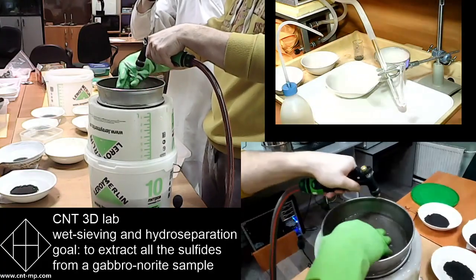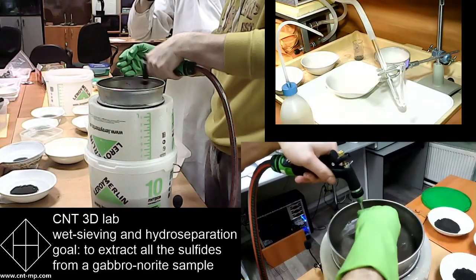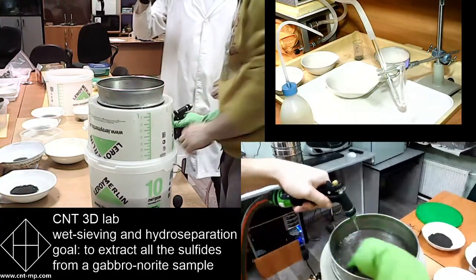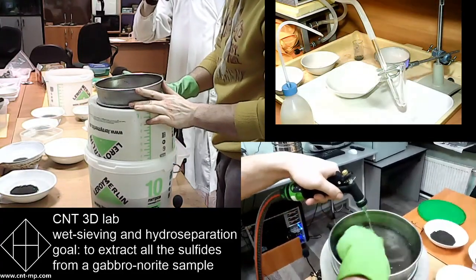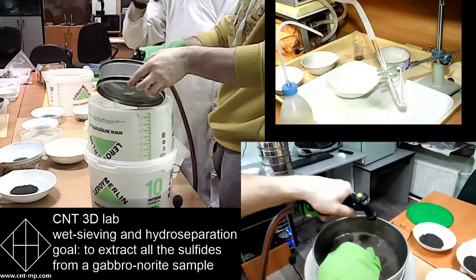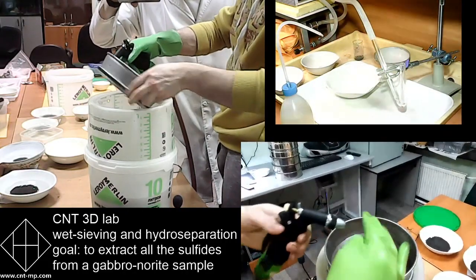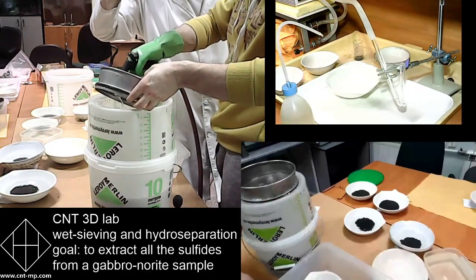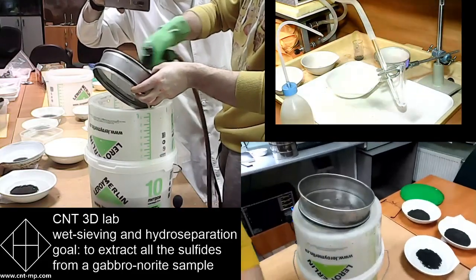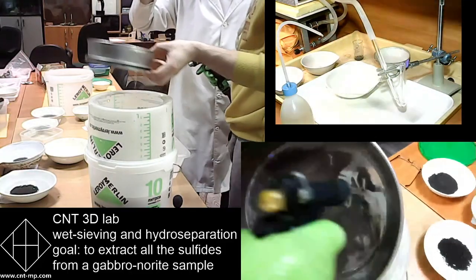That last sieve, minus 63 microns, is the most cloggy. It's not easy to clean like the previous ones, because it's very fine grain. And you can see that it's all set on the special plastic set of two different buckets. So they now contain all the material that is below 63 microns. So all these size fractions are now ready